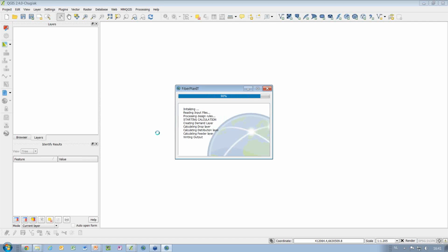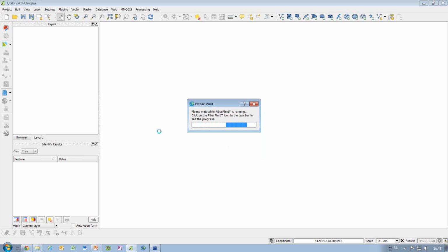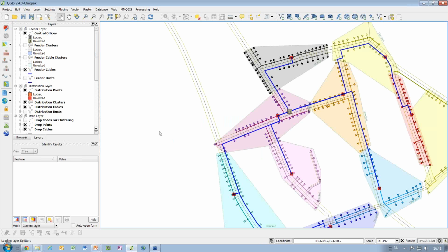Again, this is now an area of some 500 or so connections, and takes only a few seconds to calculate, but it scales up to typical POP sizes, even with 20 to 50,000 homes, in which case, depending on your rule set and the power of your PC, you may need between maybe 10 minutes and half an hour or maximum 1 hour.